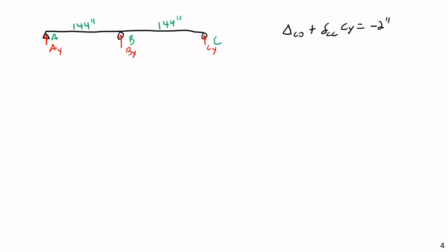So again, in our previous examples, we've assumed that all the joints are perfectly rigid. They're not going to go anywhere, they're not going to move except rotate, etc. We're assuming they're fixed immovably in space. But here we're going to say, you know what? Let's put that on its head, and instead of it being 0, let's give it a known deflection value, and then back calculate what kind of stresses that deformation will produce. So again, we know that joint C will deflect downward 2 inches, and we'll analyze that as we discussed.